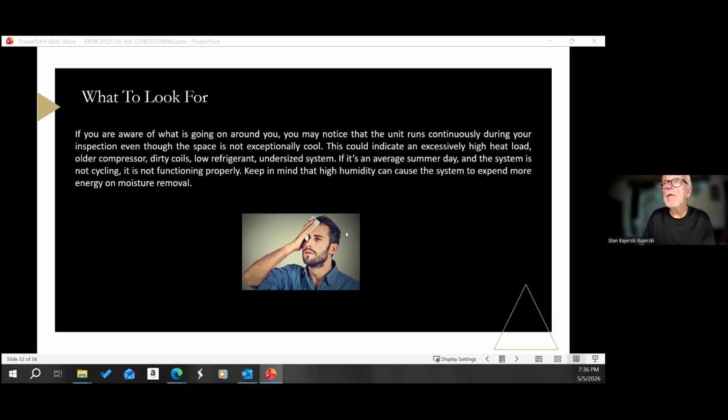Are you putting in your reports if a unit uses R22, to let them know that if the unit breaks, it'll be more expensive? To me, if it's got R22 in it, you might as well just plan on getting rid of the whole thing. Right. I've got this going on with my daughter's car right now. Refrigerant does not wear out. It leaks out, right? If you have a leak in the line set, you can fix it.